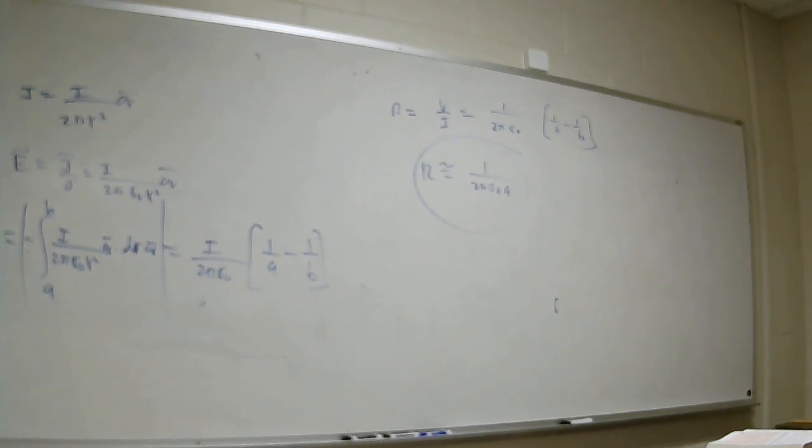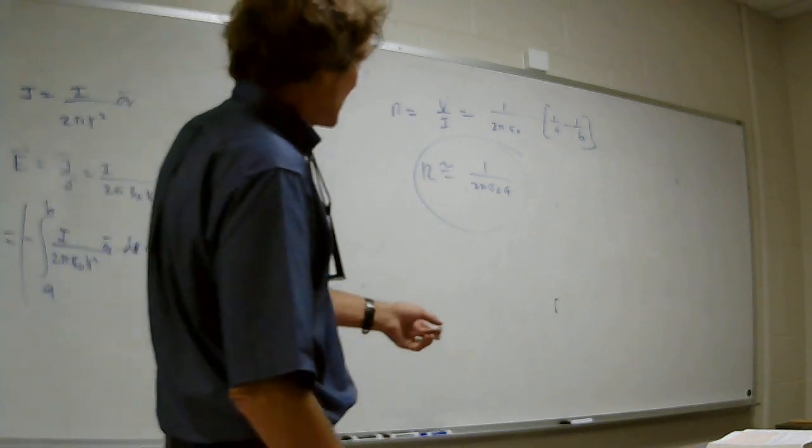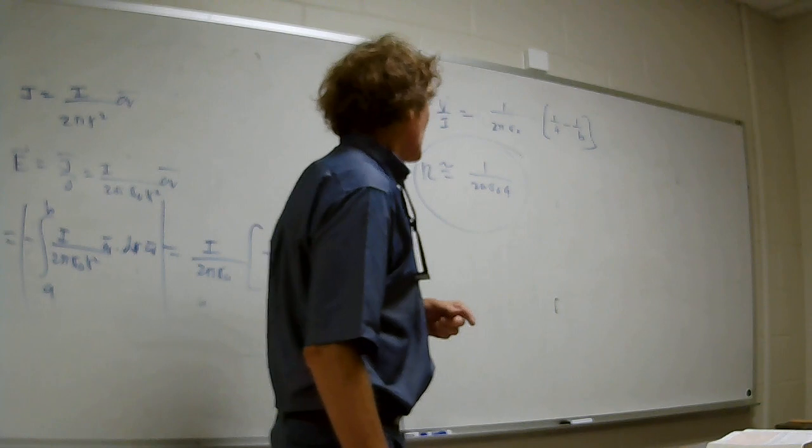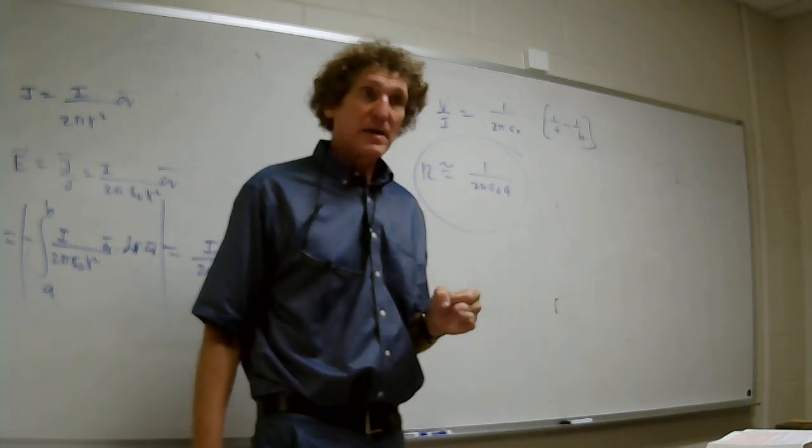You know what an electrical grounding rod is? It's about 8 to 10 feet long. It's solid steel typically, maybe copper plated, and they get it firmly driven into the ground. Usually they pound another rod in. But if this is a half sphere of a known distance, and they measure the actual resistance, then they can get the conductivity by simply taking 1 over 2 pi, resistance measured divided by A, and that would be the soil conductivity.